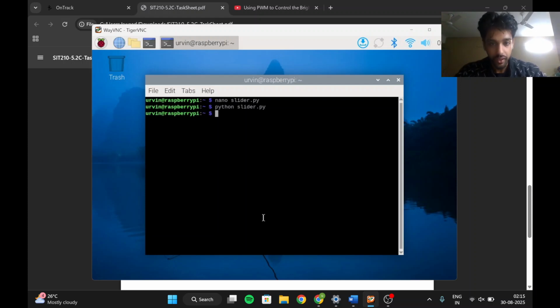It was due to the difference in using the physical pins and the BCM pins, because they both differ in design. Physical pins start from 1, 2, 3, 4, and that's how we use the physical pins. However, if we see the Raspberry Pi pin diagram, we can see how the BCM pins are labeled accordingly.